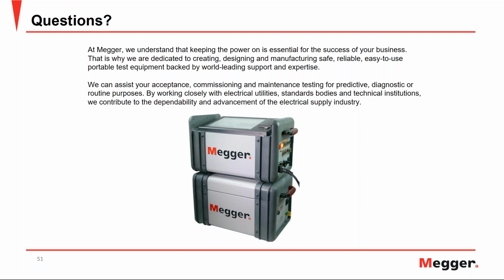Now, one thing to consider is that once the transformer is installed and in service, the insulation will deteriorate over a period of time. It is a good thing to compare against the baseline. But what is even more important is to trend the power factor values with its own power factor values from previous years.